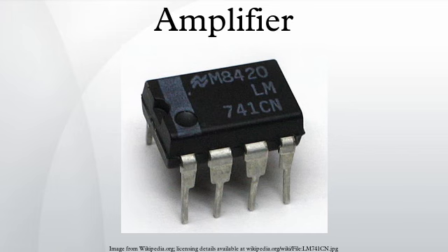Class A amplifiers generally use only one device, unless the power supply is set to provide both positive and negative voltages, in which case a dual-device symmetrical design may be used. Class C amplifiers, by definition, use a single polarity supply. Amplifiers often have multiple stages and cascade to increase gain. Each stage of these designs may be a different type of amp to suit the needs of that stage. For instance, the first stage might be a Class A stage, feeding a Class AB push-pull second stage, which then drives a Class G final output stage, taking advantage of the strengths of each type, while minimizing their weaknesses.